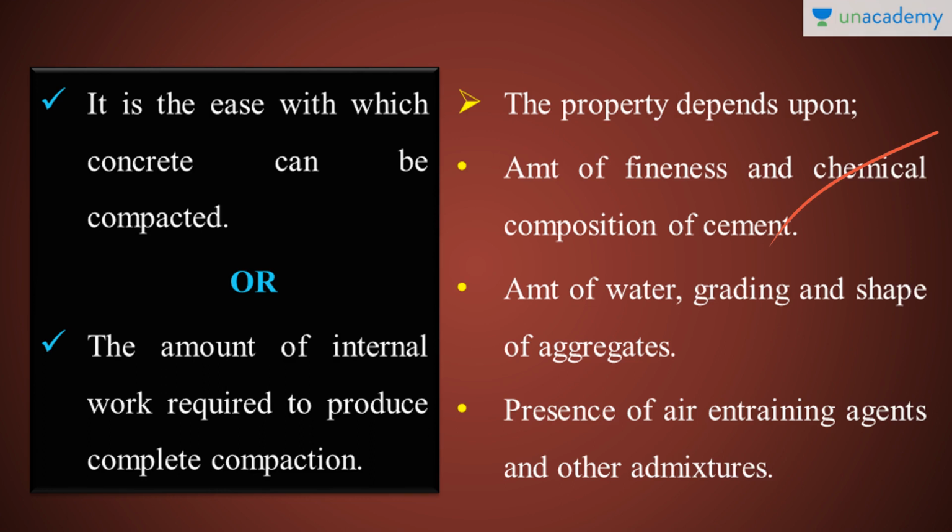We all know that workability has a very high direct effect from the water itself. On sites we can see that people just add water to increase the workability, and hence it will result in segregation. If the water content is too high, it will improve the workability, but it will result in extra properties like segregation and bleeding, which we don't want. So one must be very careful about the water content in the concrete, otherwise it might result in, as I said before, segregation and bleeding.